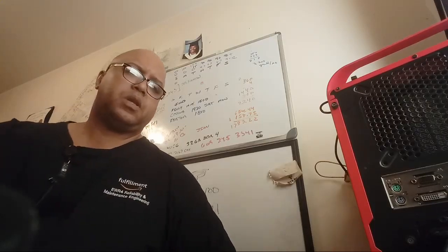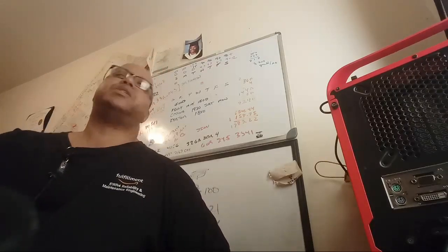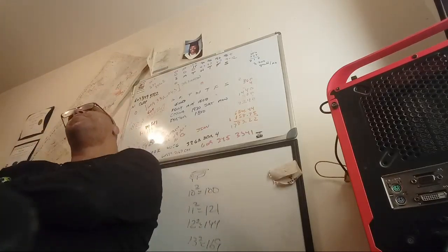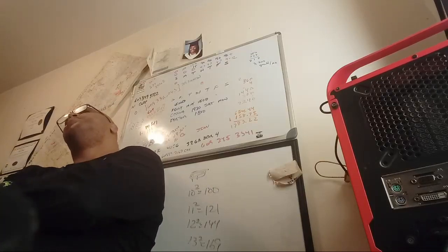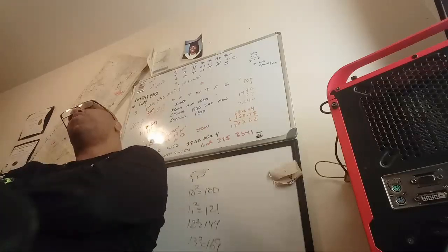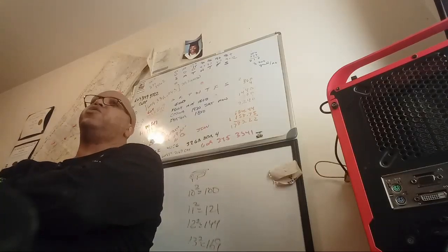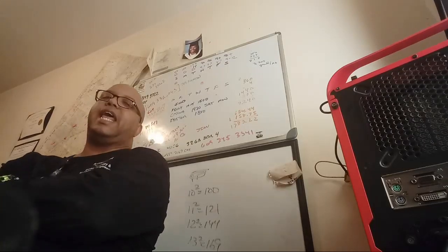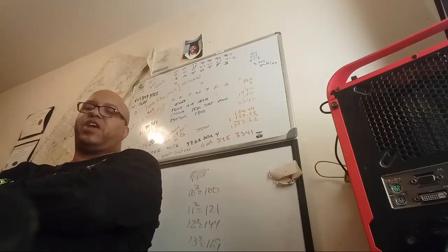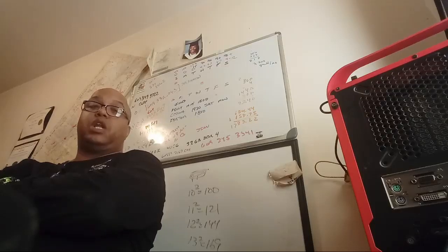Now, flaps. What is the purpose of wing flaps? The flaps can be used to slow your airspeed. Okay, drag does occur, so in landing we do get slower. We also delay our stall speed. For instance, let's say, and I'm exaggerating this a little bit, but just to give you an idea, let's say we were doing a landing with no flaps.